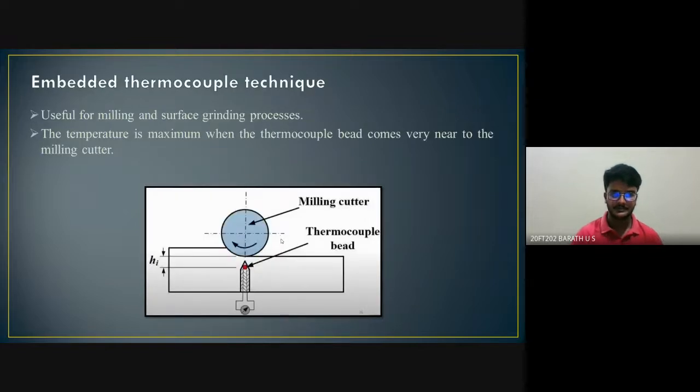The next one is the embedded thermocouple technique. In this process a milling cutter is used. We fix the thermocouple bead into the bottom of the milling cutter.